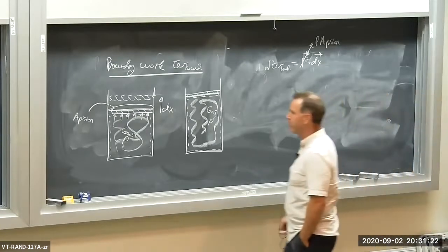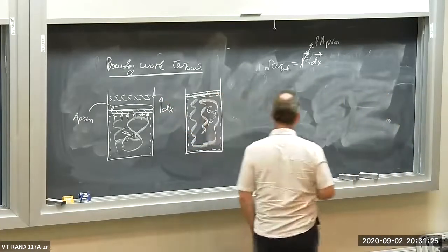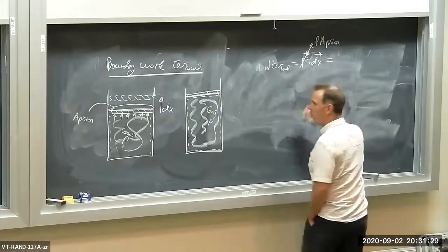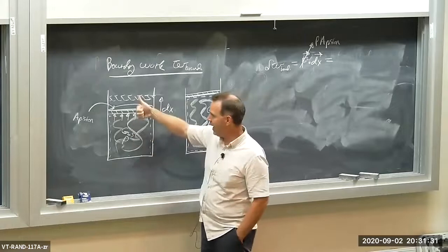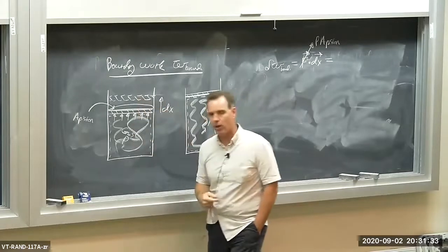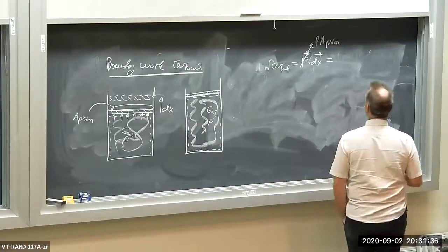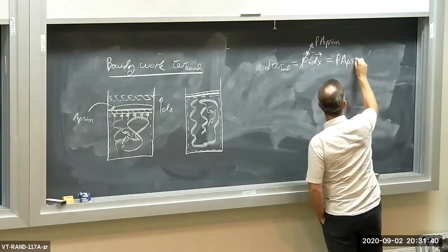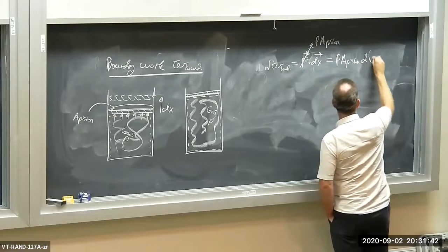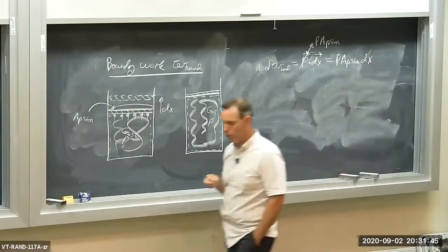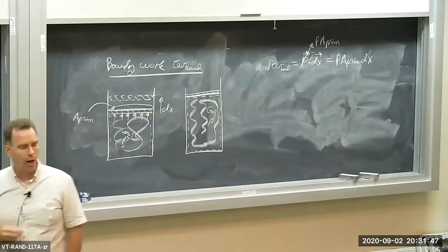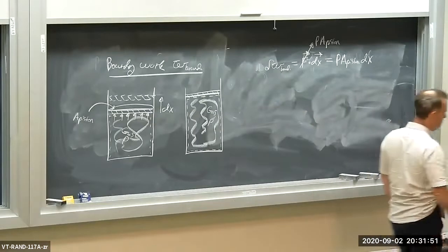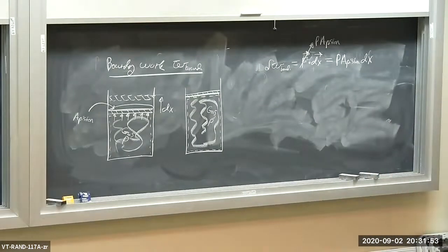The displacement, of course, is dx. And so the force is pointing in that direction, and so is dx, so they dot together, and you get pressure times area of the piston times dx. Okay, that's the differential or infinitesimal boundary work associated with the gas expanding over this differential or infinitesimal process.